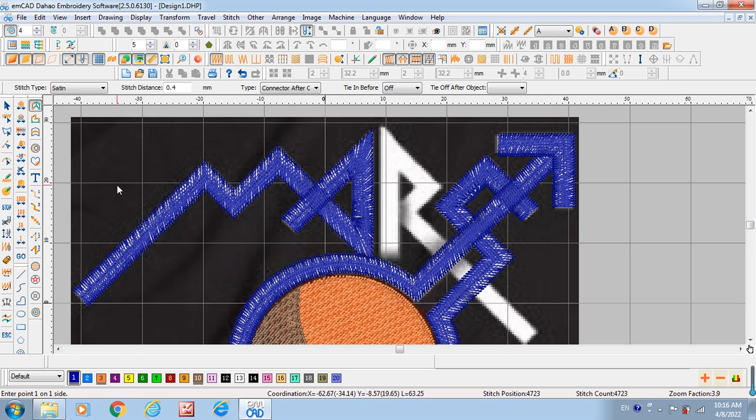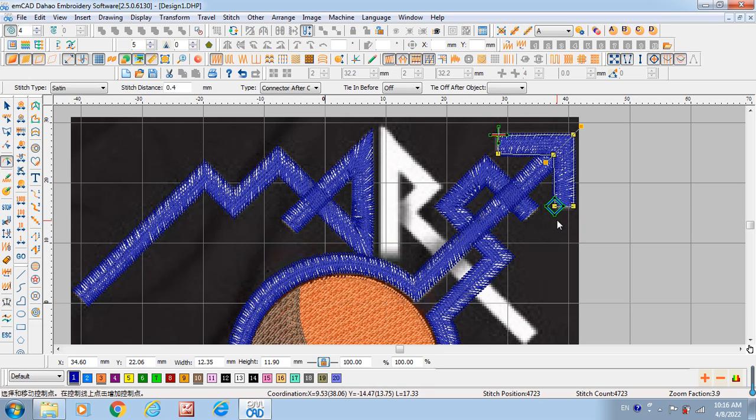As you see here, this line stops here, but this arc starts. I can go to shape. Okay, I choose the last one first, I choose shape. Then I see it starts here. It means that this one will end here and make a jump to start here. I can move the start point to here, then it will not make the jump. Okay, so I do this one here, then move it by left click and enter.